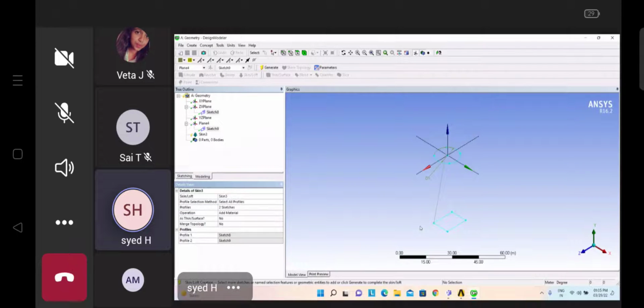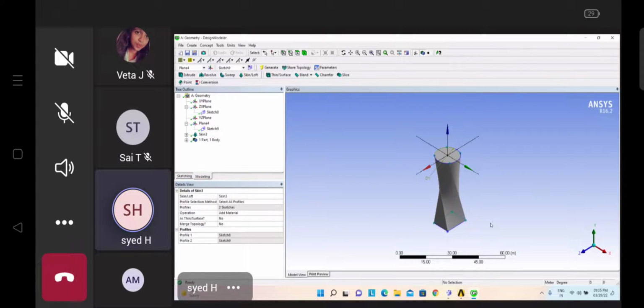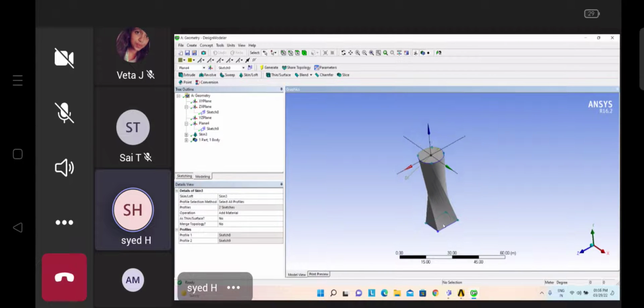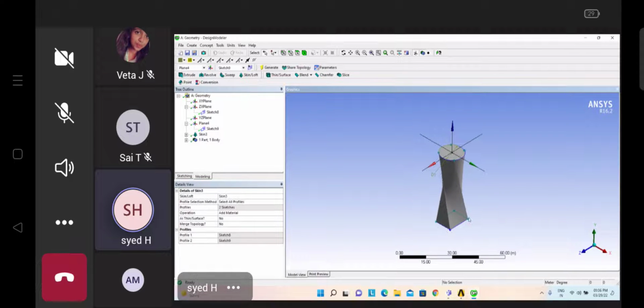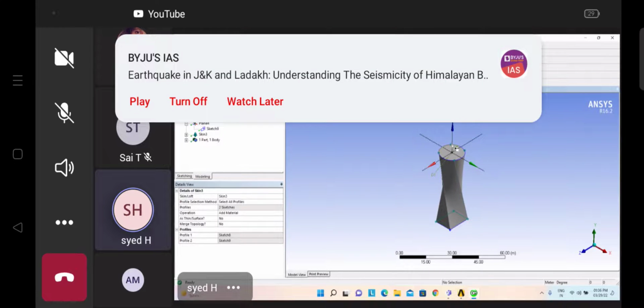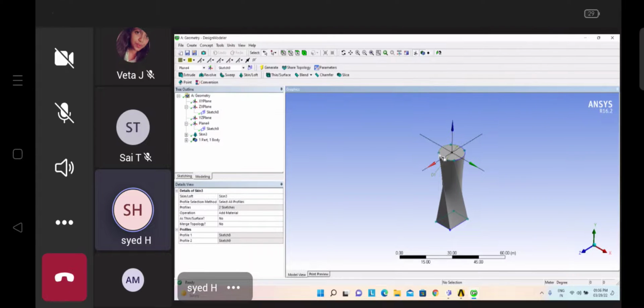Now see here, right now it's creating. Okay, just click on generate. Right now it's making twisting. Why? Because I started my rectangle like this. So here we have the merging points. This merging point is meeting with this merging point. So what we have to do? We have to make this merging point meet with this one. Means we have to do some settings here.